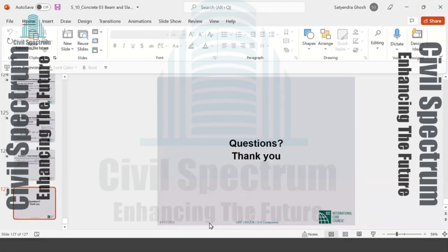And so by the time you are looking at a long to short dimension ratio of 2 or more for your slab panel, you have a slab supported on beams on all four sides, presumably a rectangular slab. If the long side to the short side of this rectangle becomes 2 or more, then bending in the long direction transmits very little load.